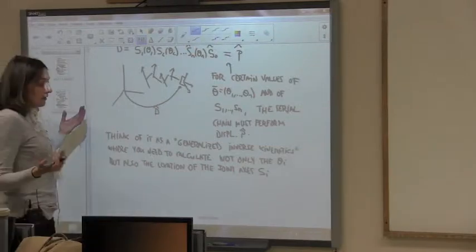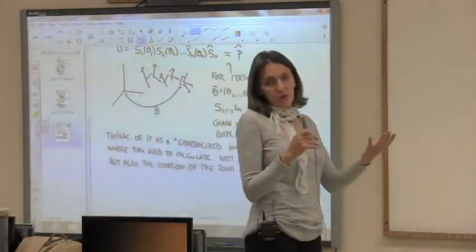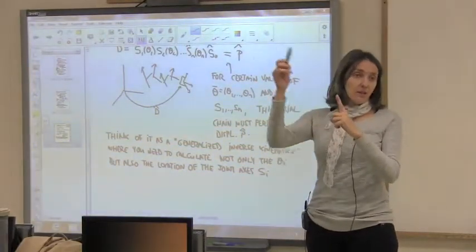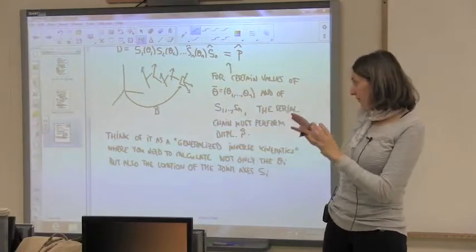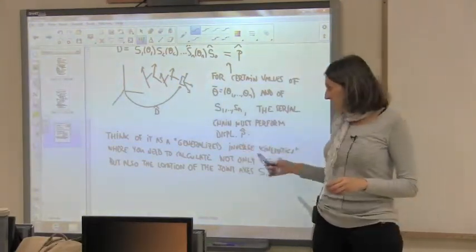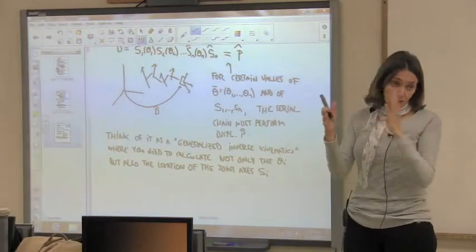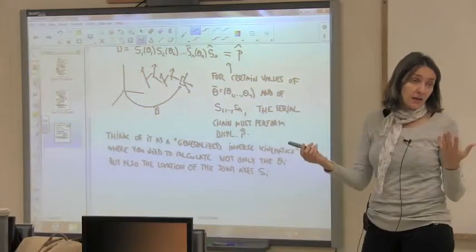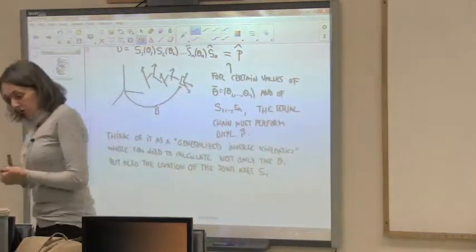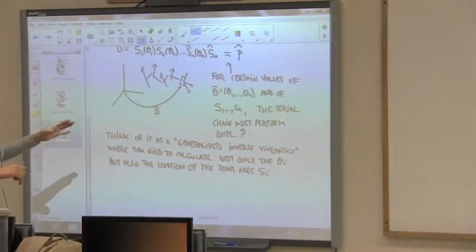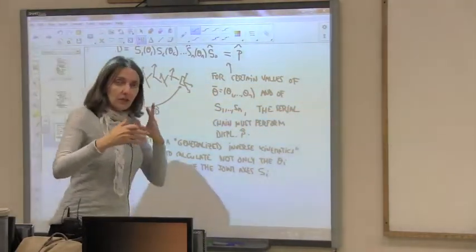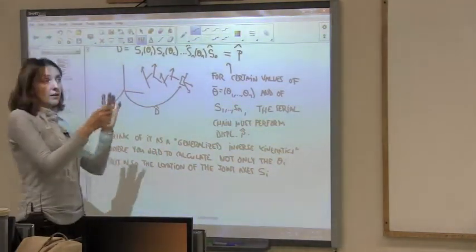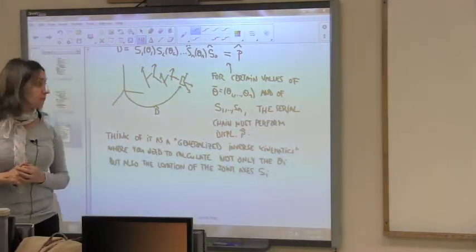So when we did the inverse kinematics, you knew what robot you were using already. You had the Plucker coordinates of your axes. You know, this axis is here, and this one is at 90 degrees. So that's already given, and then you just have as unknowns your thetas. But in this case, we don't know the axes. That's what we want to find out in order to design the robot. Will this axis be at 90 degrees to this one, or at 45, or maybe they will be parallel? And that's what the system is going to give you. So you need to solve for the actual geometric arrangement of your robot. How are your joints going to be located with respect to the other joints?